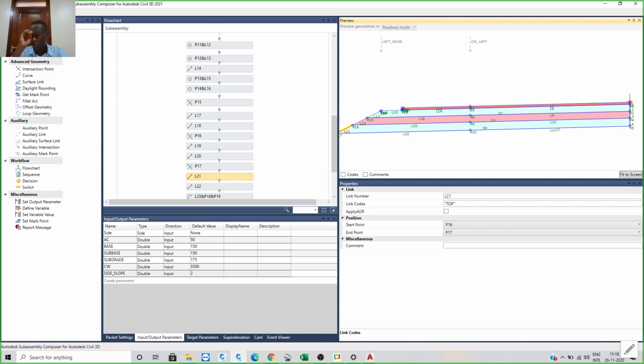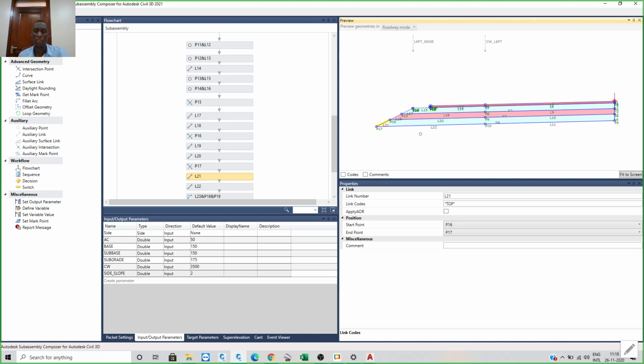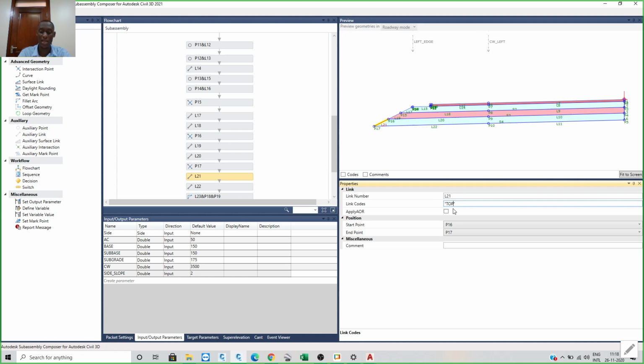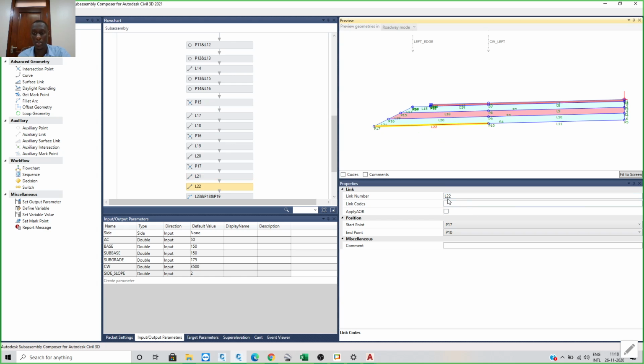If you check in your Civil 3D, usually in the corridors, it notices the top and the datum surfaces because they are the ones used to come up with the volumes. So you need to preset your top and your datum accordingly.